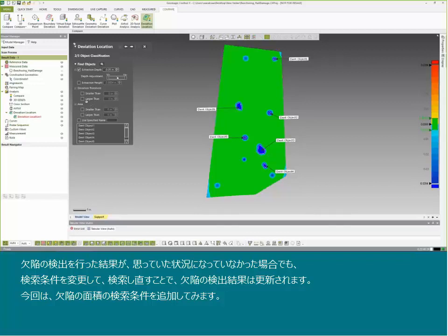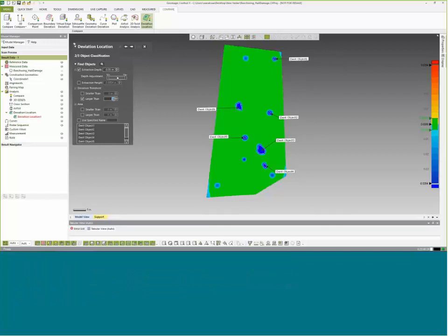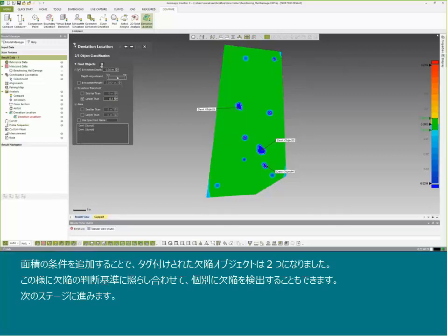I'm actually just going to use deviation threshold and say we're going to look at stuff that is of a certain depth overall that's going to flag an item for us to investigate in person, essentially. So let's do this, and I'm just going to make this like minus 0.1. So we'll do essentially a 1/8 inch here. So we can check that out.